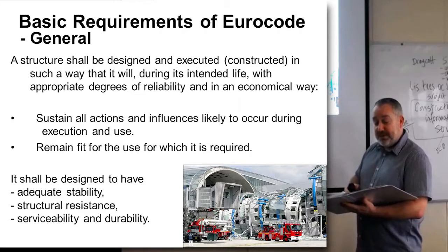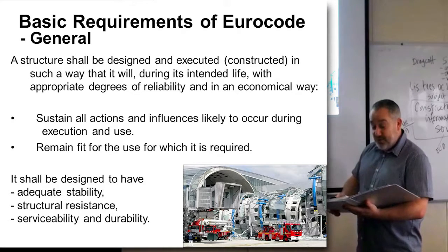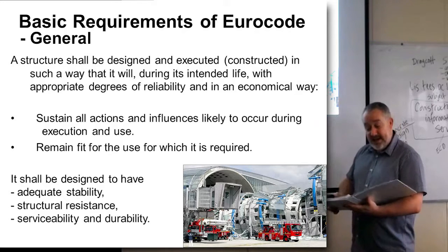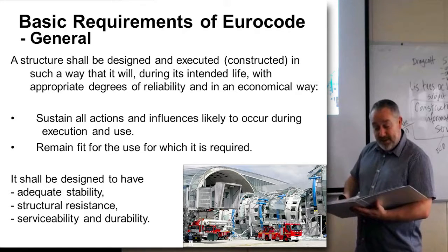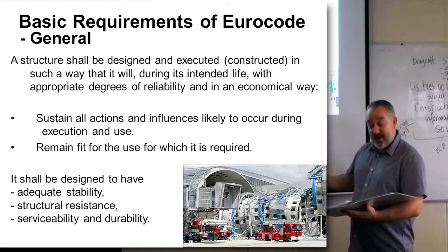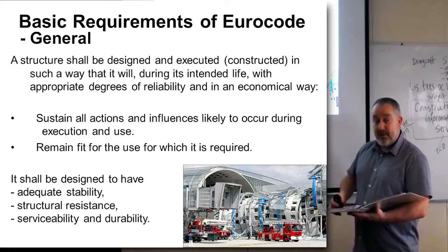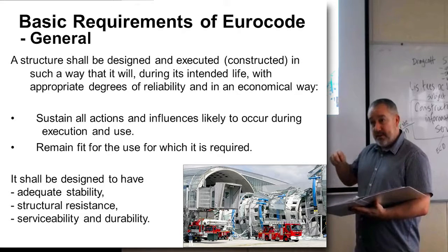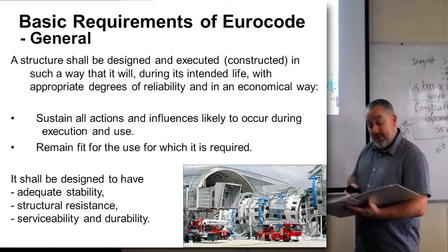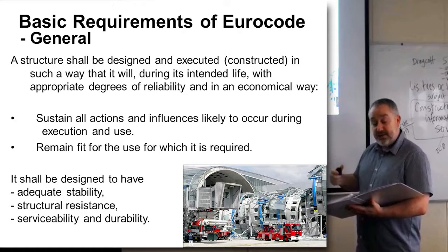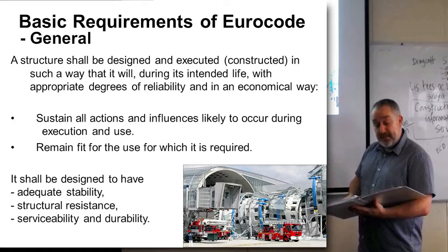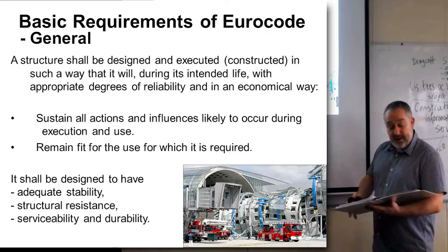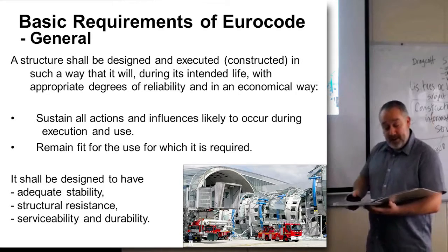A structure should be designed and executed in such a way that it will, during its intended life, with appropriate degrees of reliability, sustain all actions. Now you realise that the word loads, we use the word actions with the Eurocode, so it needs to sustain all the loads and influences that are likely to occur during execution and use.